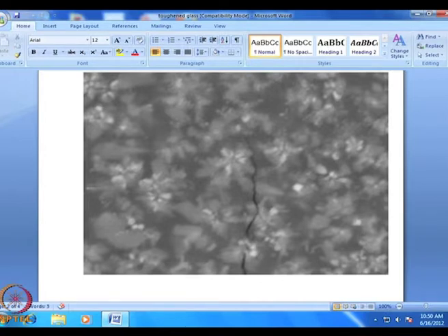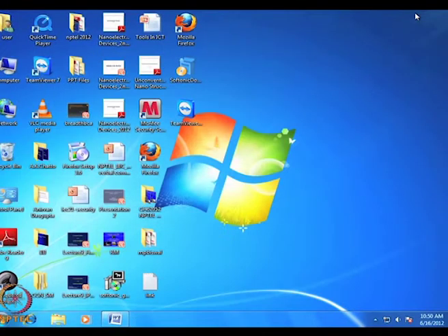These are different crystals inside the glass. The crack has to go, it has to break across these crystals, follow the grain boundaries, break these crystals. For example, here it has to fracture the crystal, it has to break the crystal here, spend huge amounts of energy before it can proceed. I shall take up this glass ceramics later, possibly today.